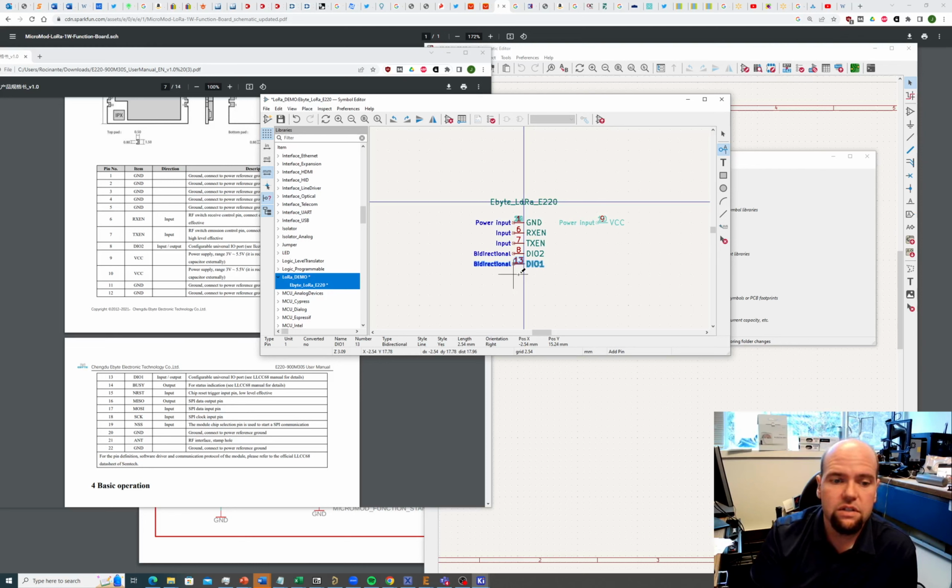So a lot of students, almost all students, make little mistakes. They use the wrong pin number, something like that. It can be really tough to find them. Everybody assumes everything's going to work until it doesn't. And so part of developing an understanding of PCB design is learning not to trust yourself, learning to say, I didn't see anything wrong, but that doesn't mean there's nothing wrong. So assume you messed up, assume you screwed up, assume you need to find where you screwed up and make those changes before making those changes requires you to do a whole other PCB design.